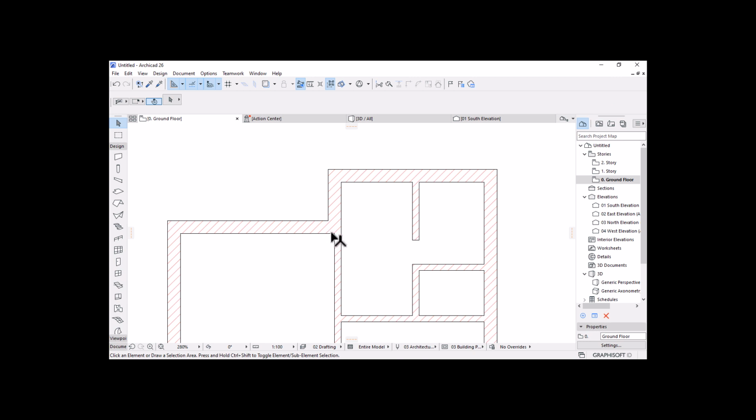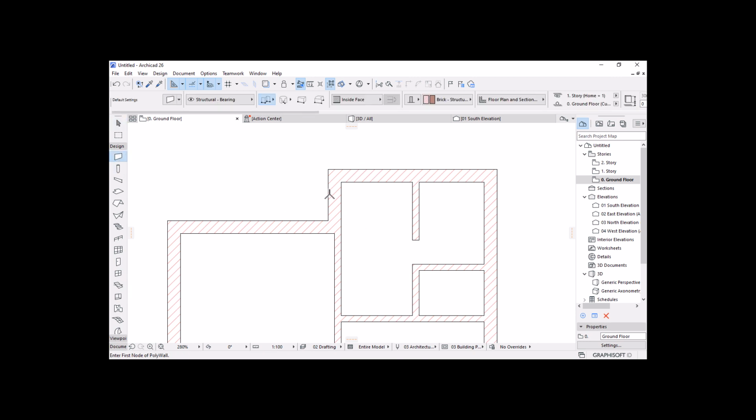So we have to have another wall coming from this side to there, but this wall is going to be an internal wall. Am I together? So I'm going to activate the wall tool. By default, ArchiCAD will pick previously properties of the element that you've placed. In this case is this 115 wall. So if you scroll down here, you would see we're still in an 115 thickness of our wall.